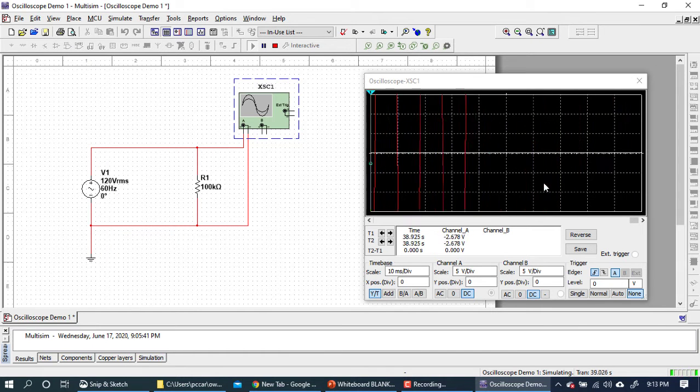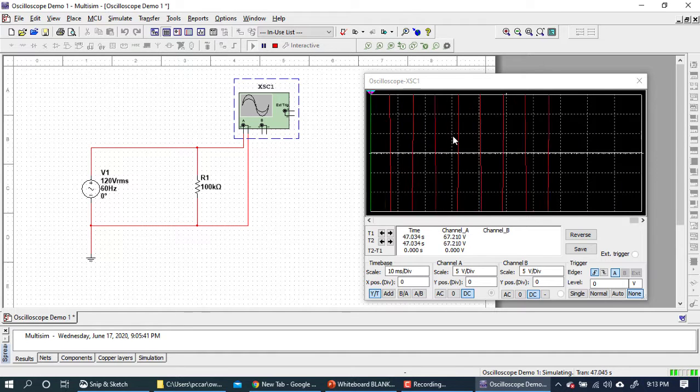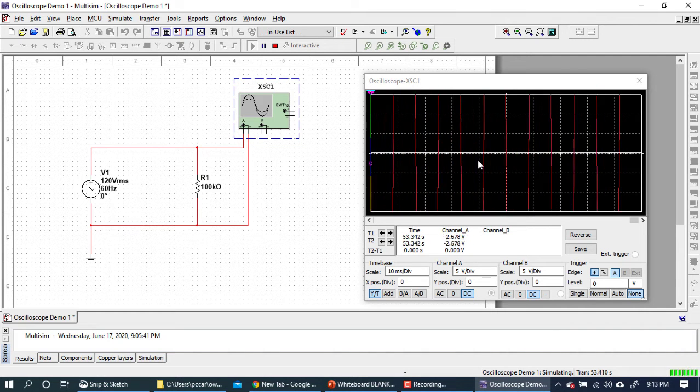So we've got a couple things going on here. I can see that this waveform looks too large to fit on the screen. So that means the voltage of this waveform is much higher than what I currently have the oscilloscope set for. Now you also have to know a little bit about an oscilloscope. It's fundamentally designed to measure two things.